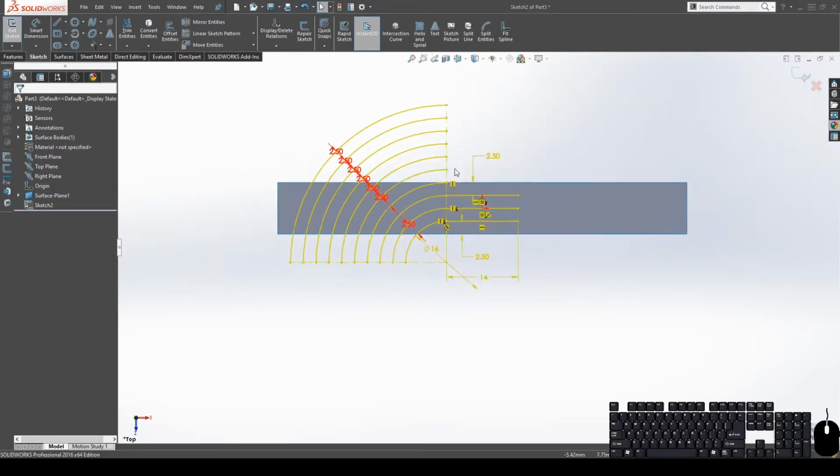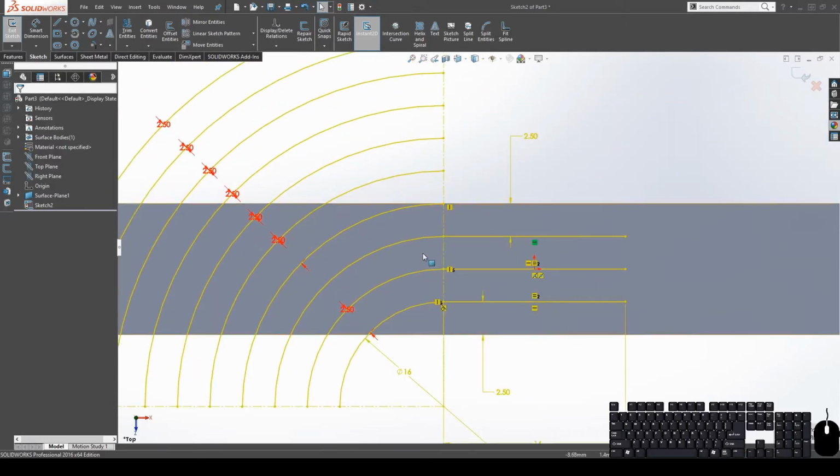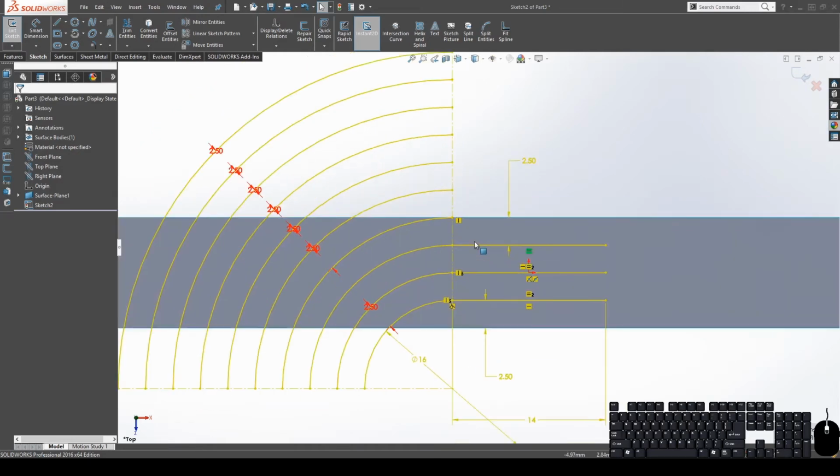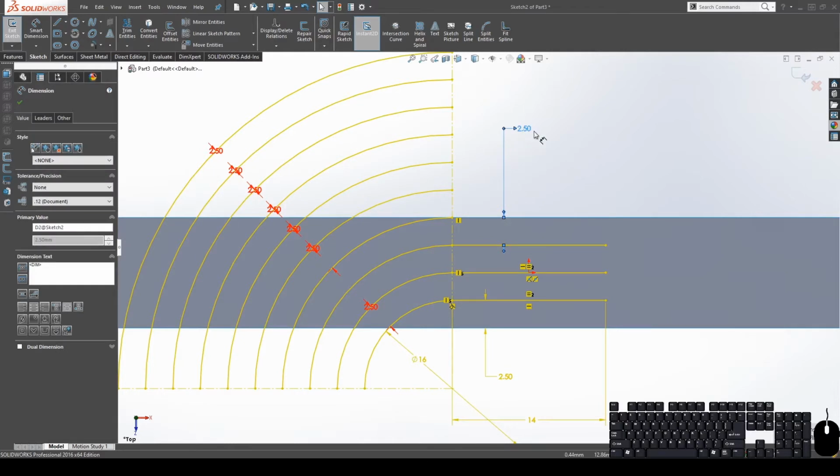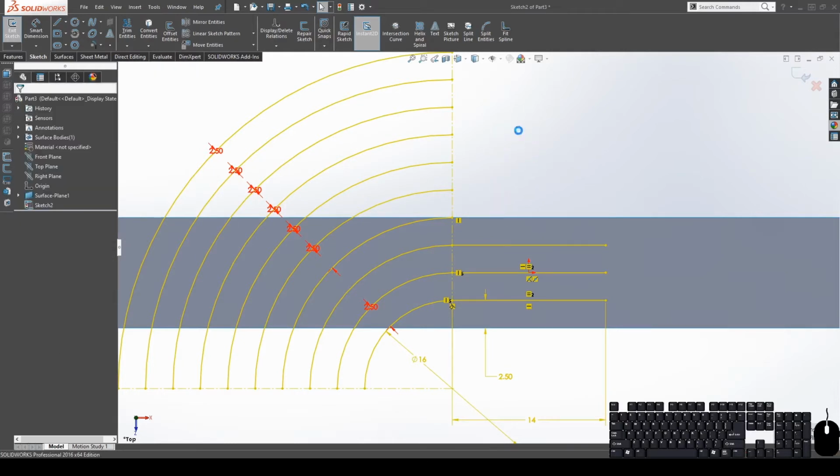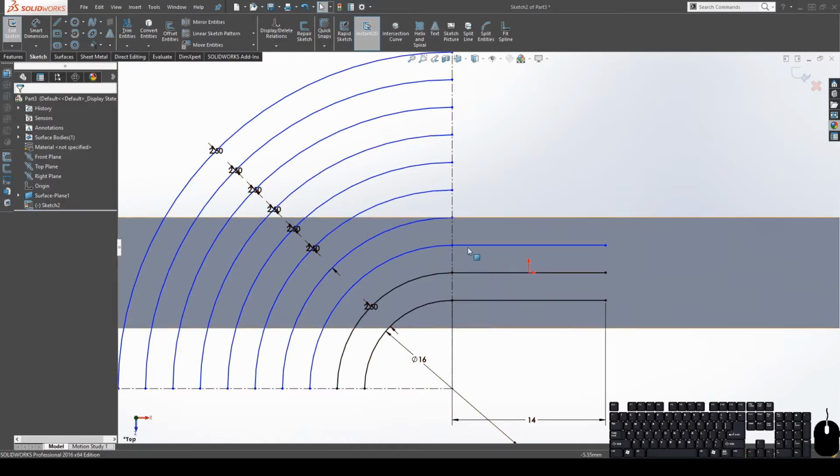All right. So it's okay if you get this. Typically, what's happening when you have an unsolvable sketch is you have too many conflicting dimensions. So in this situation, I'm going to assume that it's probably the fact that there are multiple dimensions that are telling me the same thing. So let's delete this, and then let's delete that. Okay.